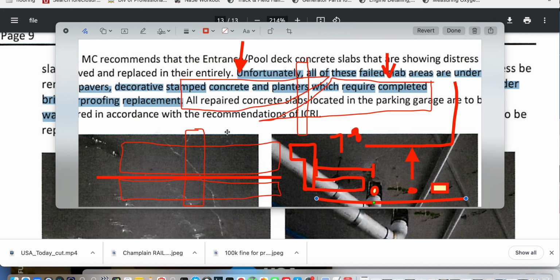Remember I talked about in the previous video that if you have rebar, let's just use 2 pieces, even though I do think it's 2 directional down here at the bottom. He just happened to hit 1 direction. If I was to move this top bar, it doesn't do anything. It doesn't move the bottom bar. Neither with this one. What needs to lock them together is the concrete. The concrete here locks these bars together, so if you move one bar, you move the other. And the concrete acts as the bond between the two of them that makes this whole marriage work.